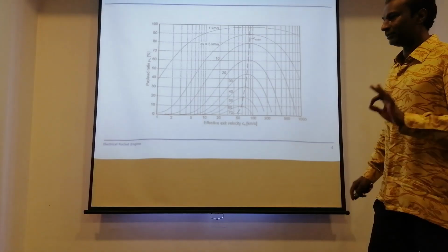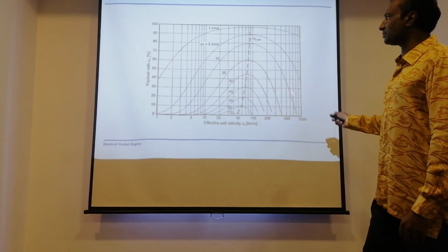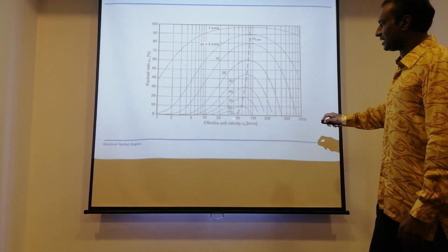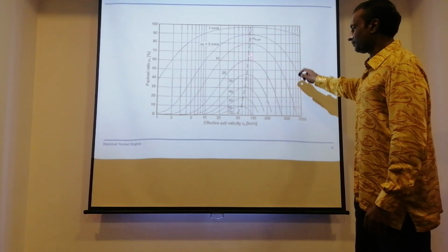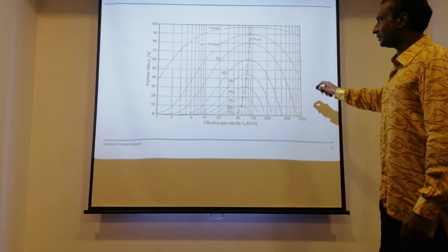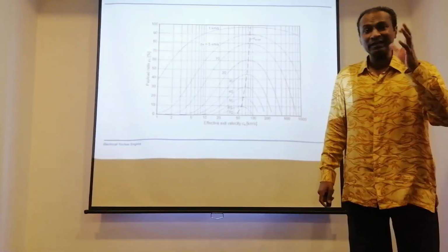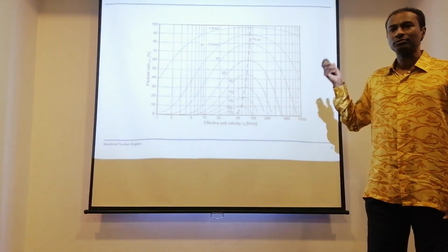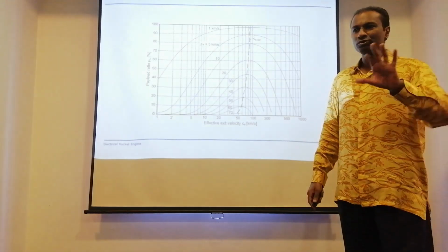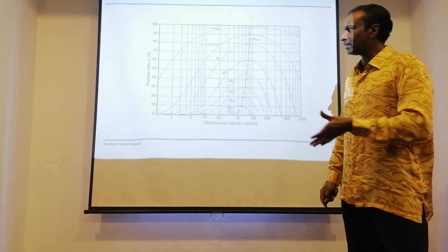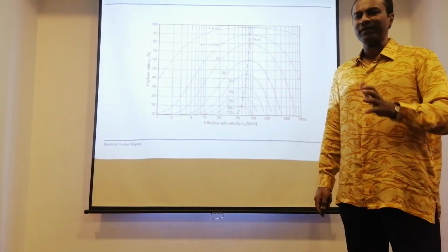But one good thing in this graph is the effective exit velocity. For all the peaks which have been optimized, you look at the CE, more often than not it's about 50. It's an extremely good graph, because it tells you that no matter what engine, for most of the engines you have, your optimum will be about 50 effectively.